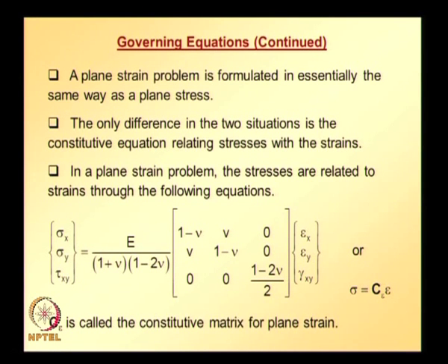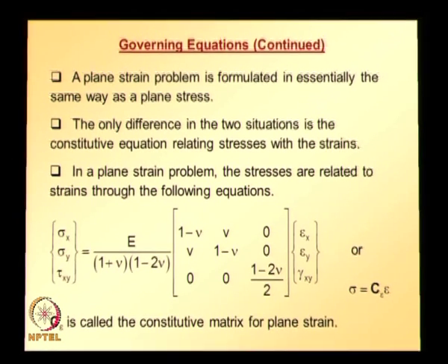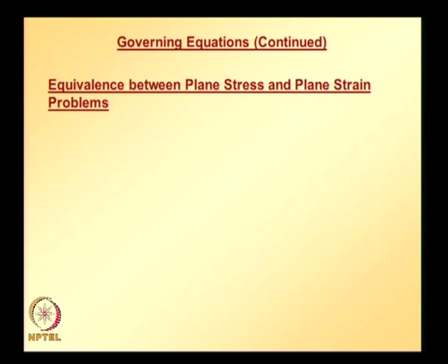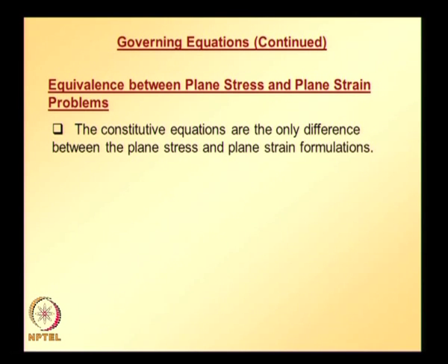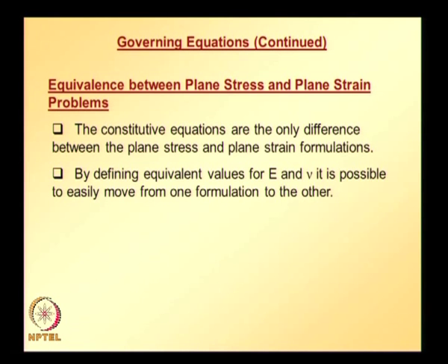Once we have a set of equations for the plane stress case, how do we quickly convert those equations for the plane strain case? The constitutive equations are the only difference between plane stress and plane strain formulations. By defining equivalent values of Young's modulus and Poisson's ratio, it is possible to easily move from one formulation to the other.